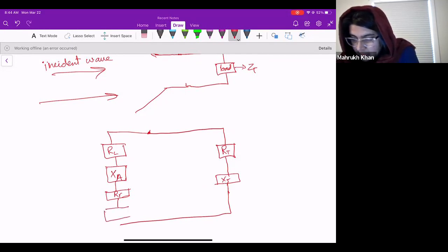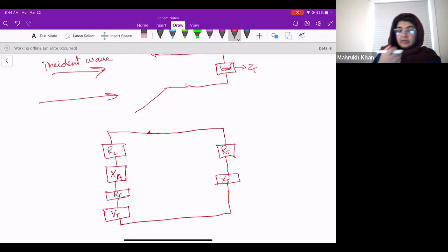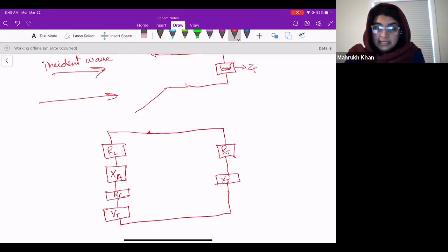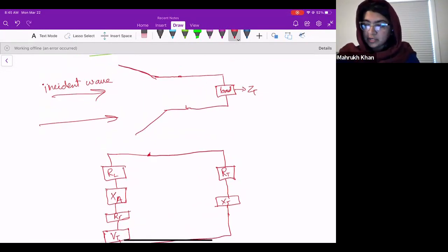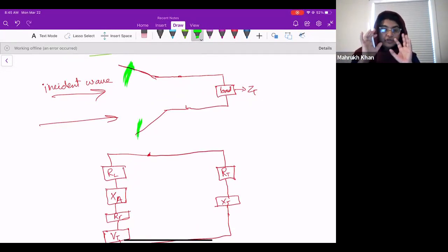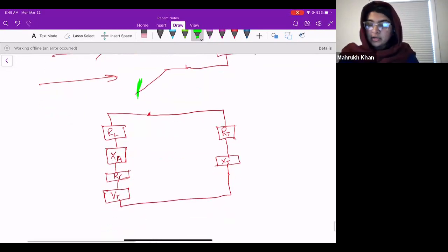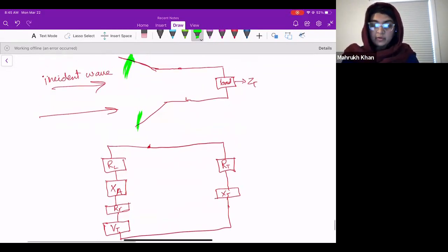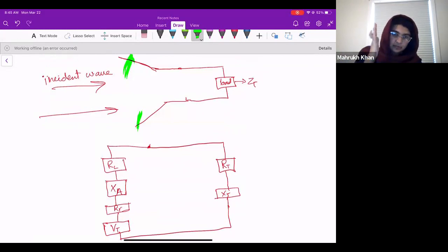And the thing that differs here is VT. So in the transmit scenario, you have VG at the generator side. Here you have VT towards the receiving side, because when the incident wave comes in, the voltage will be induced in the arms or at the antenna terminals. So that's why in the receive mode scenario, you have VT at the input terminals.